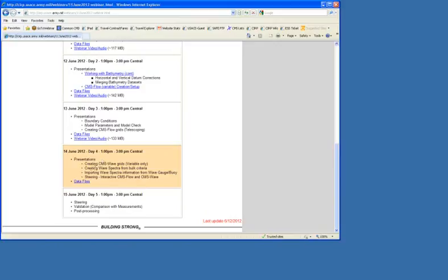We're going to be covering creating the wave grids. It's very similar to what we've already covered, so that'll be a good time to go back over some of that same information. Also importing wave spectra from buoys and gauges, and how to create wave spectra energy files from just the bulk criteria. And if there's time, probably go over a little bit of how to make the CMS flow, CMS wave grids interact with each other through a long simulation.